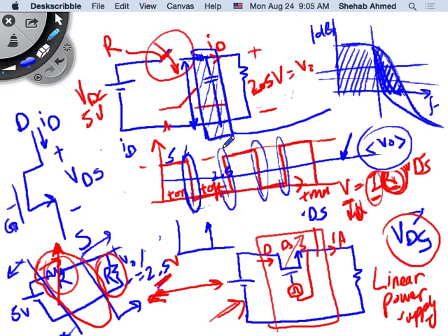The amount of ripple in a power supply output depends on the load. For example, if you are just operating a resistive heater, where you just want to heat the room, and you put power through this heater that operates on, say, 10 volts DC, do you really care how much ripple content is in this application? I don't really care at all.